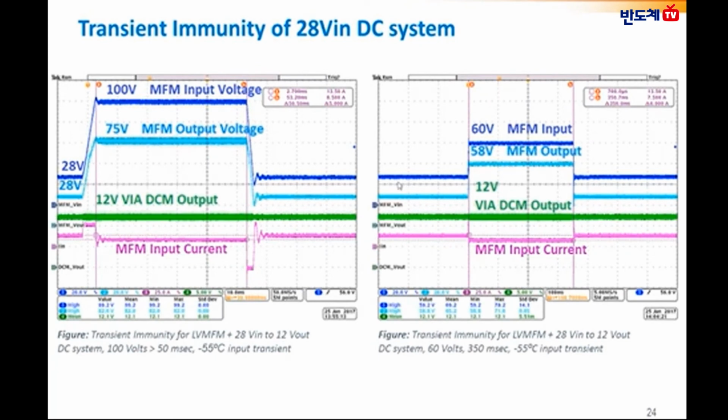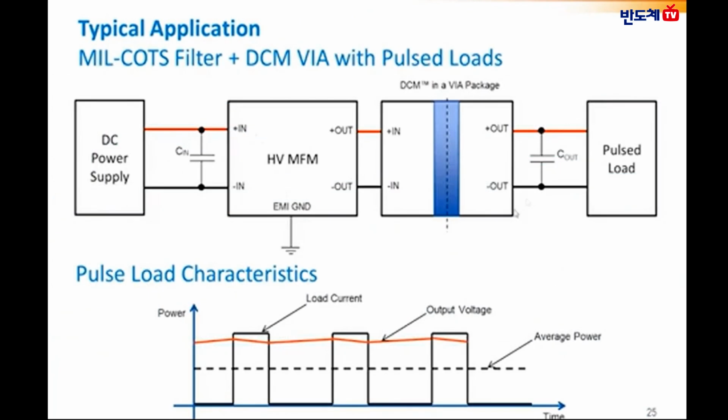A poor layout can cause an increase in parasitic capacitances or coupling capacitors formed in between the PCB traces, and can potentially trigger the radiated emissions. Therefore, here are some considerations that need to be kept in mind while designing the PCB boards.